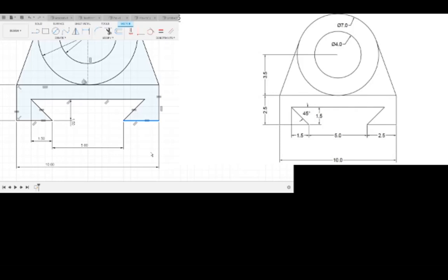So in regards to the symmetry constraint, Tom, something that you'll find with SolidWorks is that it doesn't have one, but instead, for certain parts of your model, you can just make one half of it and then mirror it, which also has the same effect, and is always a little bit more effective when you're making more complex things. So then you don't have to do it twice. You just do it once, mirror it, done.